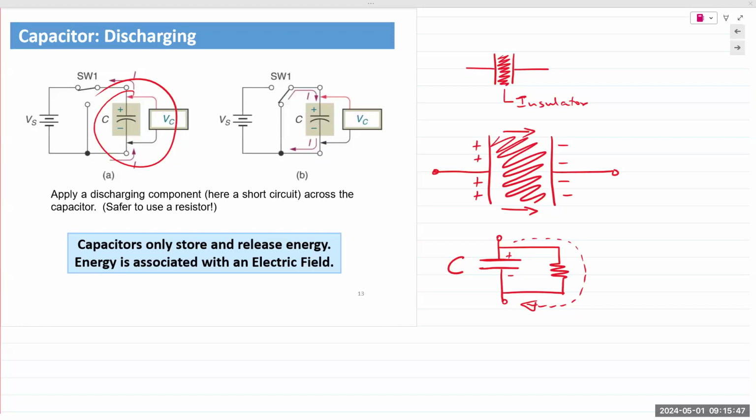A real-life example would be what happened a few years ago with the Samsung Galaxy Note 7. Do y'all remember? Exploding phones. If not, look it up. In the pursuit of making phones thinner and smaller, somebody at the battery design center decided to make the walls that separate the cells very, very thin. So it short-circuited the battery cells inside that phone. Because it short-circuited, all of that energy was released at once and it got overheated. If it doesn't stop, the energy continues to be released until all of it is gone, resulting in an explosion.